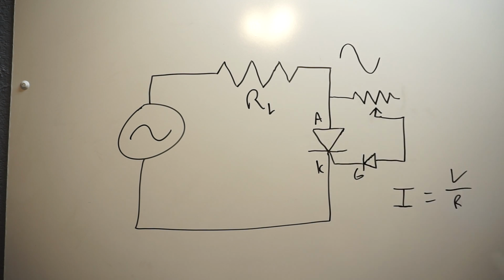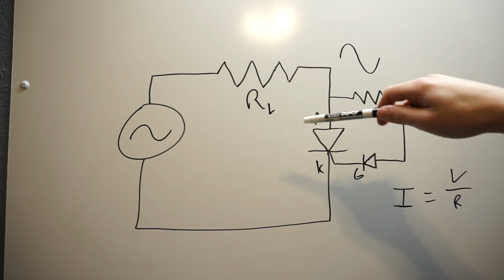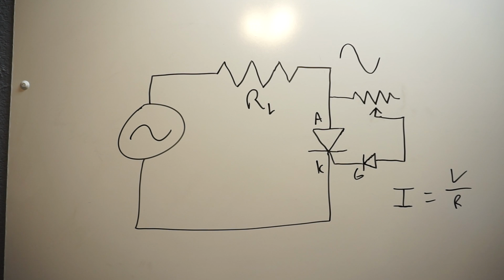you have a lot of power factor issues that come into play, and also your SCR could potentially kick in at the peak of your sine wave in inductive loads, and that causes large surge currents and other issues like that. We'll look at that in another video, but right here I just want to talk about the SCR. I don't want to talk about design issues with these SCRs, but essentially here's what's going on, right?